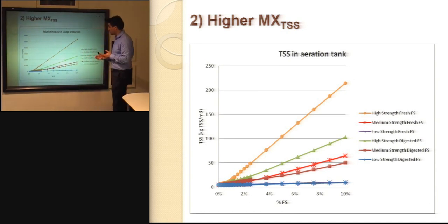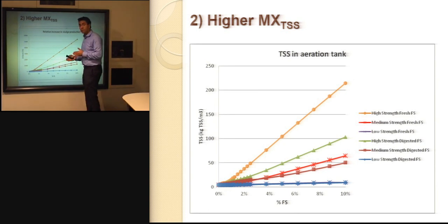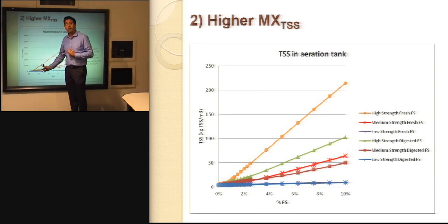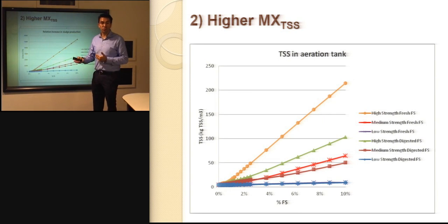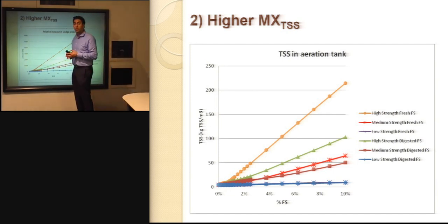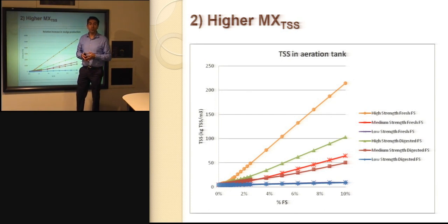And this not only implies the need to have the required equipment, pumps, to extract the sludge, but it also implies that we need to have in place the required sludge handling facilities to deal with this sludge. Remember, the sludge cannot be disposed of straightforwardly. It needs to be, for example, dewatered. It needs to be composted. It needs to follow different processes to reduce the volumes and to reduce the aggressivity of these sludges.